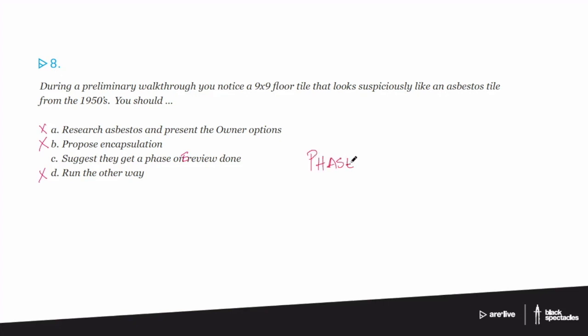So what this is, a phase 1, is when specific environmental engineers who have specific training will go through an existing site. There might be already a building there, might be just an open site. And they will take a look and they'll do a quick search that looks to see, well, what has been on that site? Was there a dry cleaner there? Was there a printing press that had lots of solvents and things like that? Was there a gas station? They'll look at the history of the site and do maybe a walkthrough.